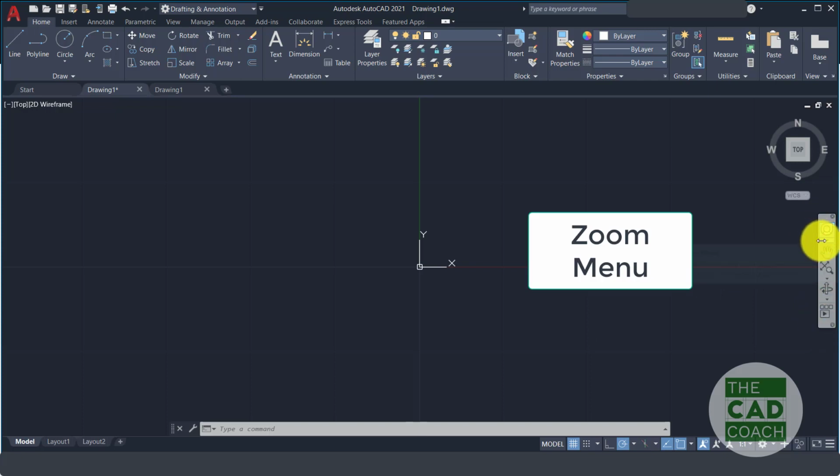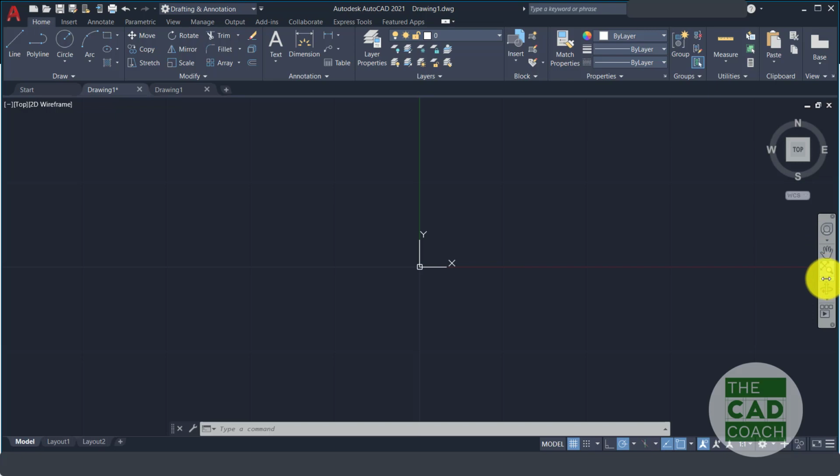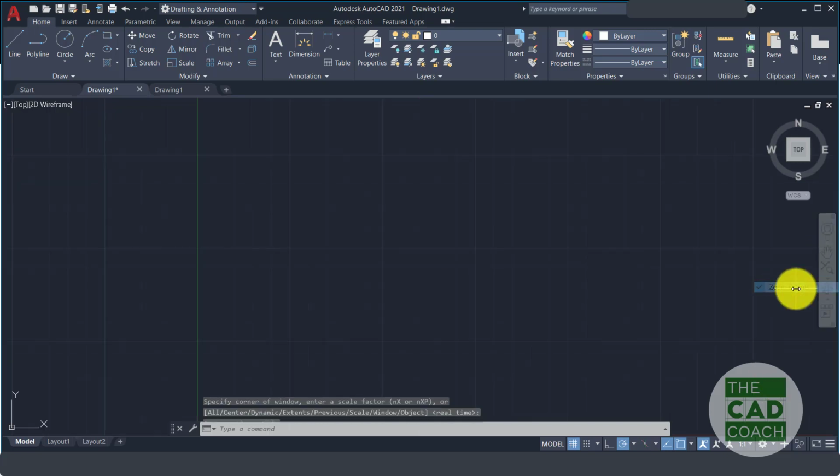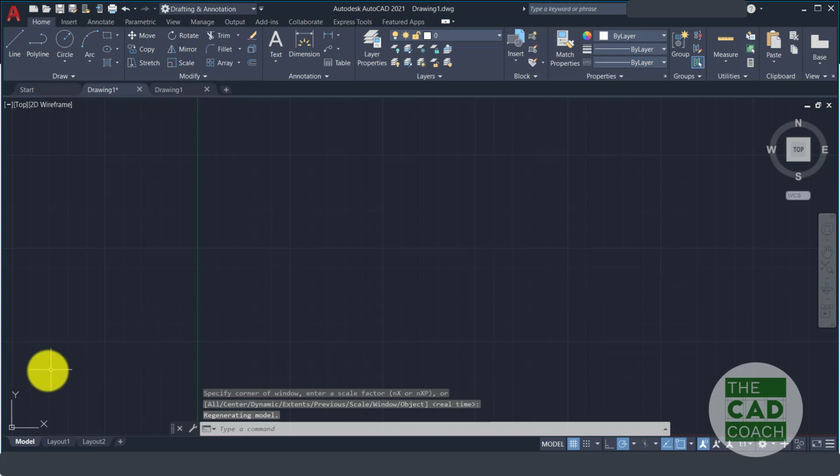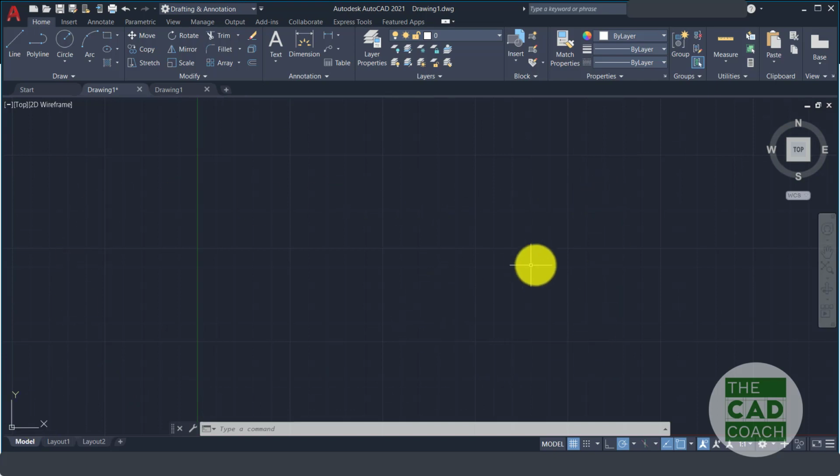The zoom menu has a steering wheel. We have zoom extents. We have many different types of zooms. In this, zoom extents is the default thing. So zoom extents goes to the default setup. In all drawings, it is shown from the origin. Okay, this is model space, and now I'm coming to the